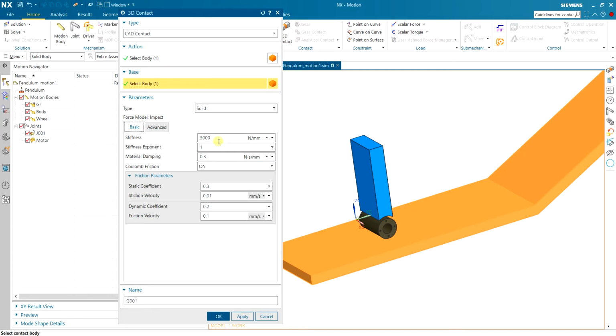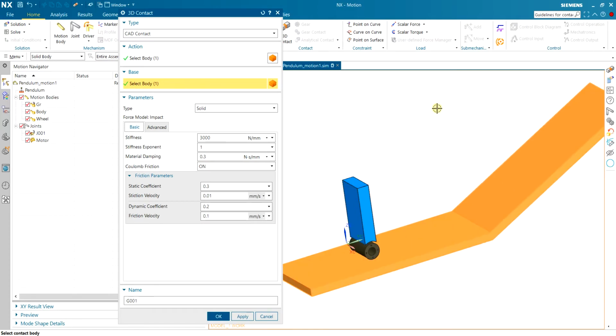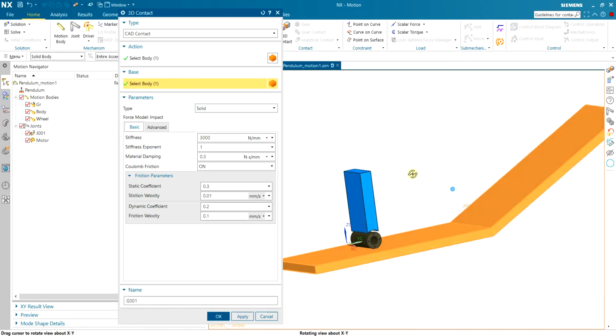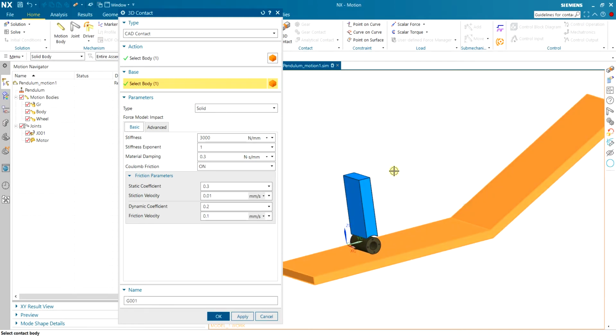And then you need to set these parameters, and you need to make sure that the contact is stable and will converge, because contact has its own algorithm and it goes inside its own loop, and if it doesn't converge, you're gonna have problems in the whole simulation.